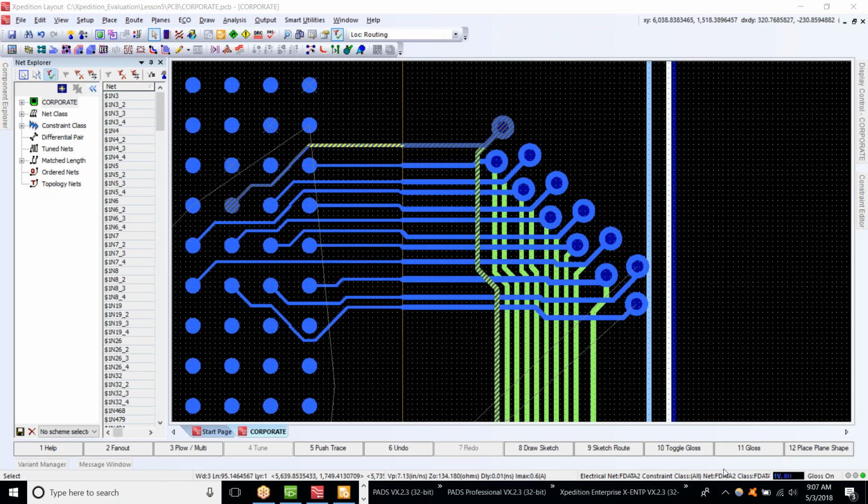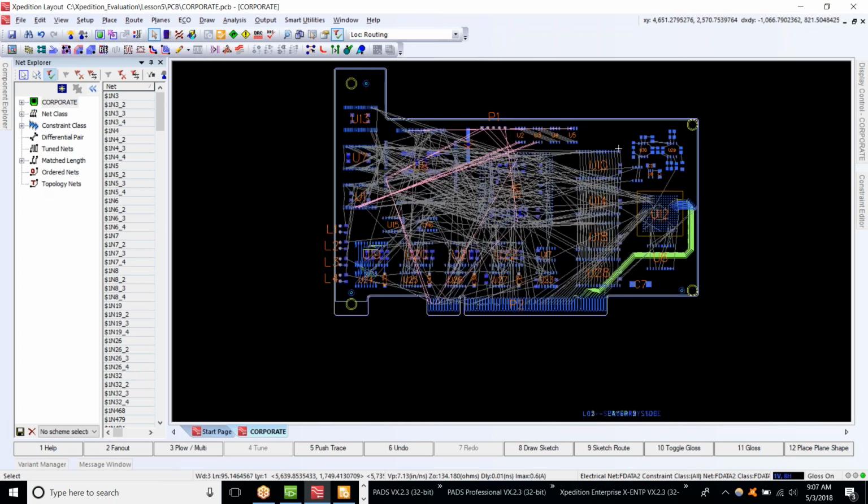And Thomas, I hope that answered your question. Yes, area rules are typically used for breaking out of BGAs or other fine pitch parts. Some people use them for higher or larger spacing between traces, for example, on a certain plane area, or certain areas away from board edge connectors, anything like that. You can really use it for anything, but probably the most used case is for breaking out of fine pitch BGAs.